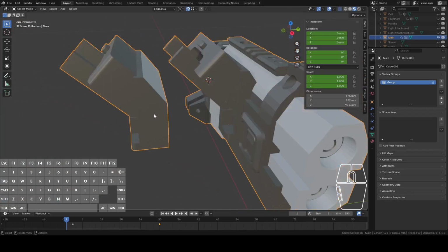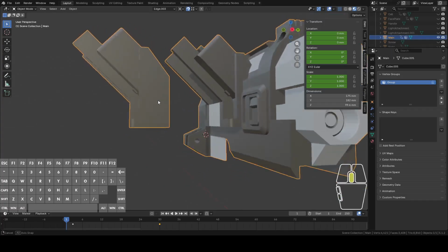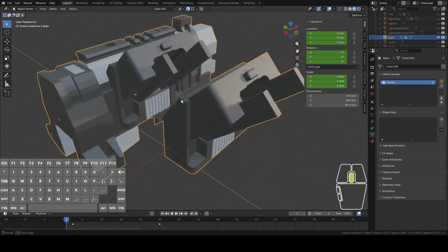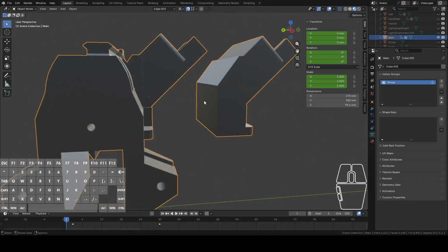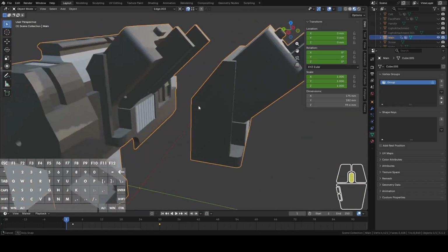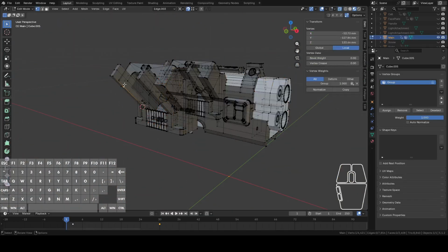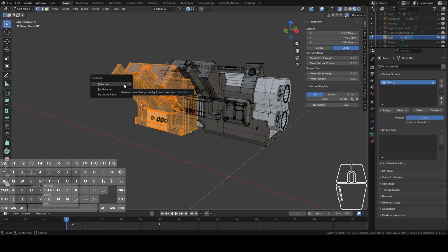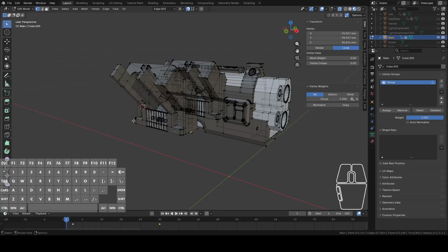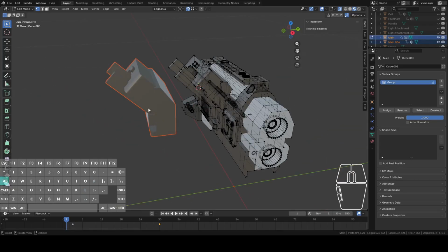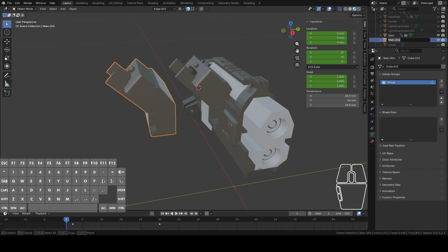I'd like to print it standing up, but I'm not sure if this angle will be conducive to that. We might end up printing it with this face down, perhaps, but we will see. And let's separate the selection with L, clicking on one of these vertices, hit L to select all, and P, and then separate selection, and we will call this the cell port, just to distinguish.